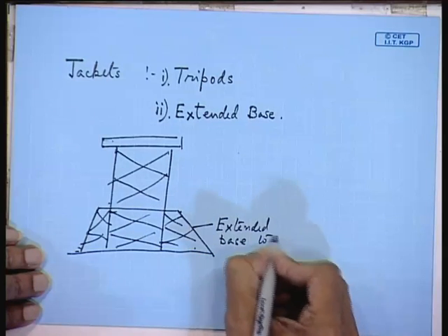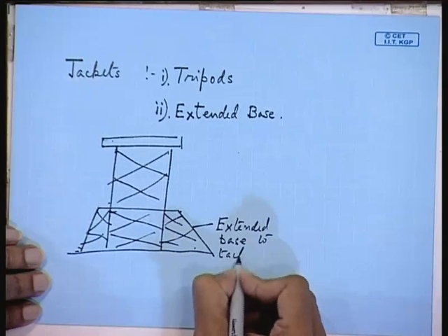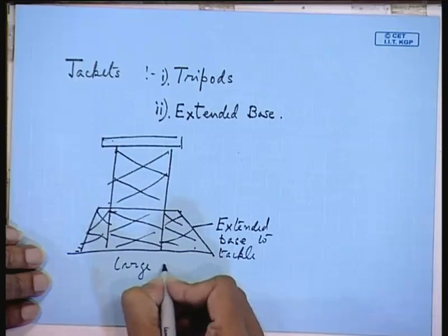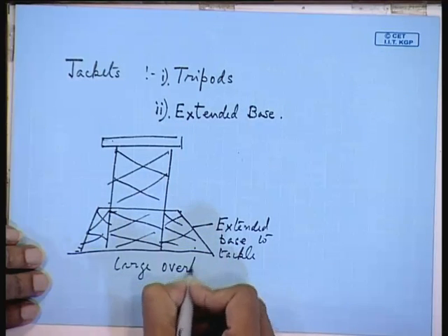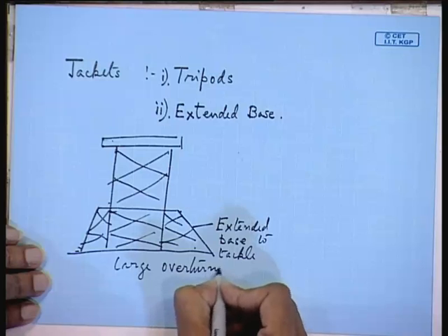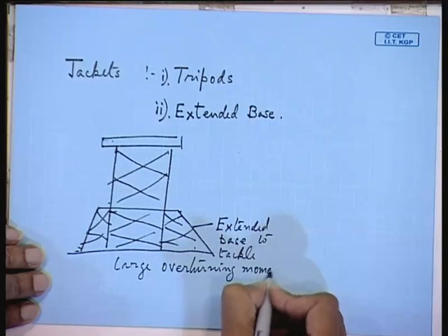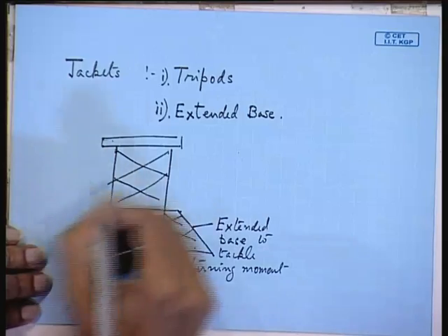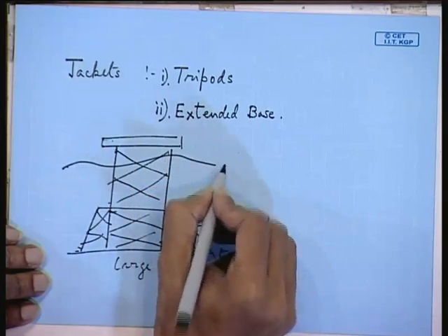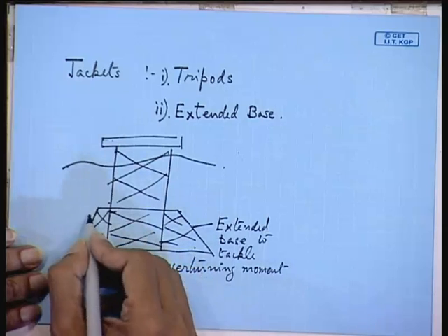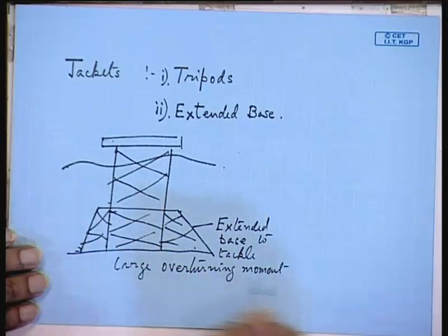Extended base to tackle large overturning moment. So, your waves will come somewhere here. So, in order to tackle this overturning moment, you extend the base.